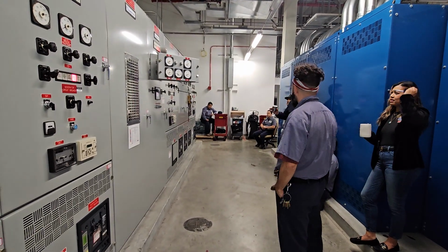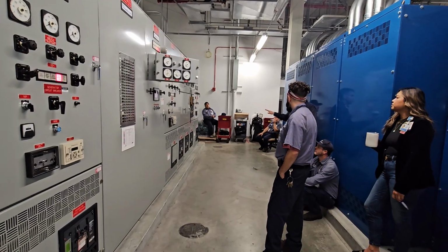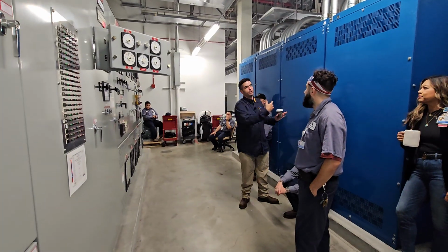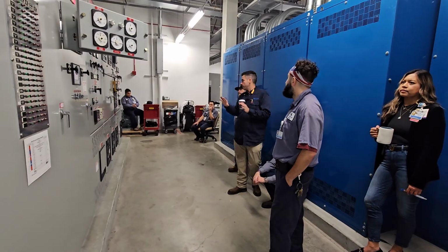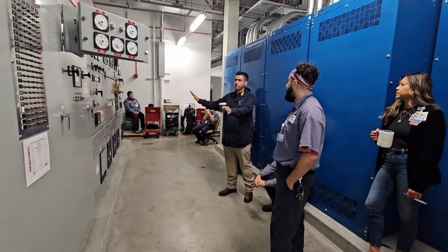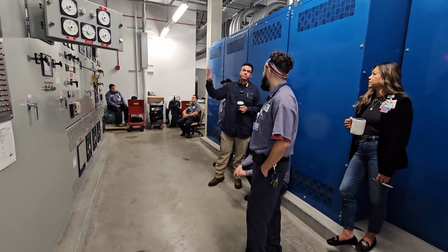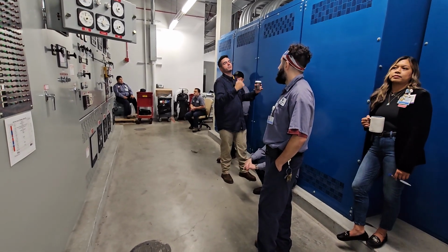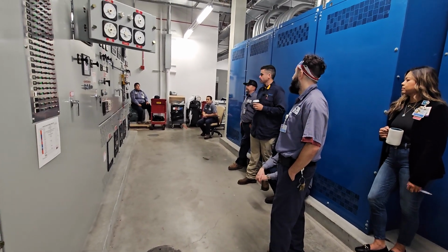Okay, let's think about this scenario. We lost the PLC. We are already with emergency power on. The next thing you're gonna do is leave this alone and go check your ATSs, right? We'll go into that training a little bit. So whenever you run through this scenario, you come here first. Because if the generators won't start or don't close to the bus, then there is no power at the ATSs. So once you have both generators running and closed to the bus, go back to the ATSs and start checking: this one transferred, this one didn't transfer, so we go and take care of that. Questions so far?